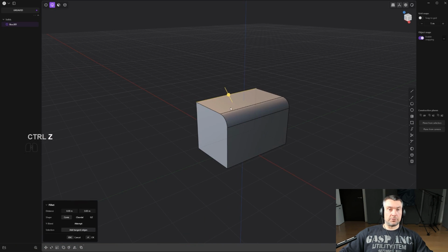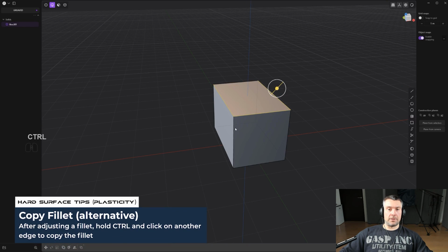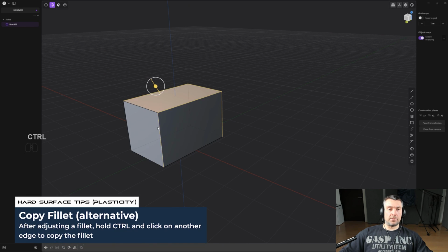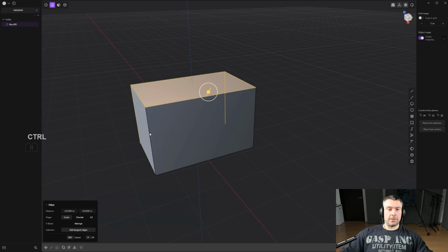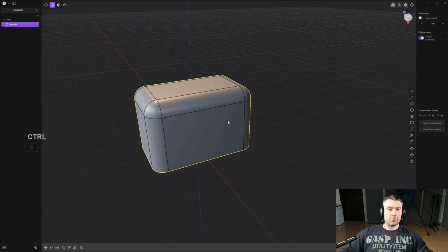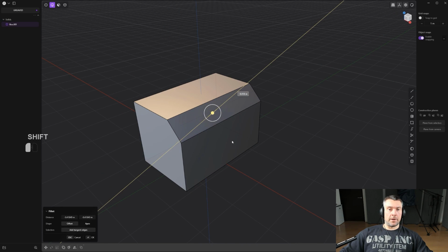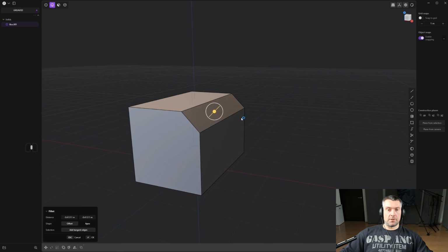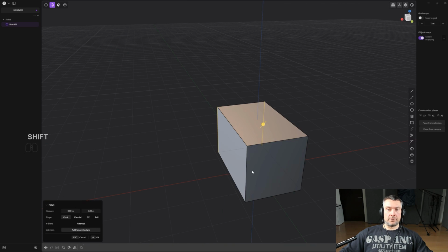You can also press Control, so when you're beveling, you can hold Control and select whichever edges you want to add to this beveling equation. And until you confirm this bevel, you can just keep on clicking, right? And approve, and you're good to go. You do chamfering the same way, just drag the other way, right? So that's chamfering.